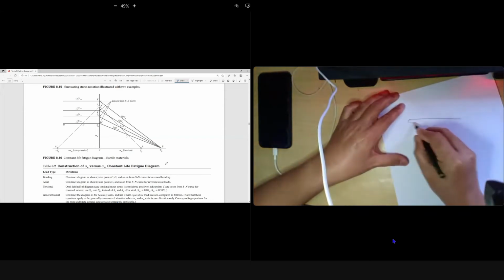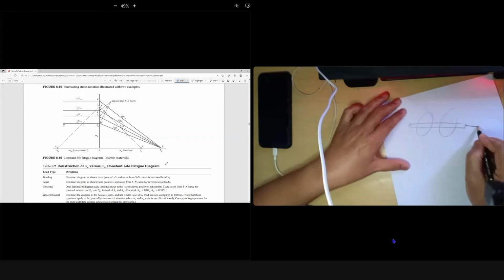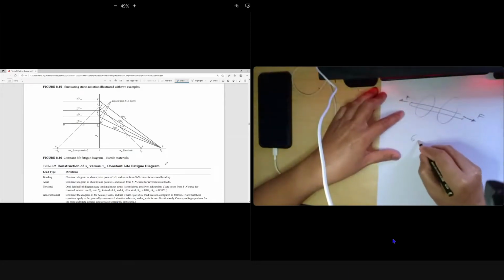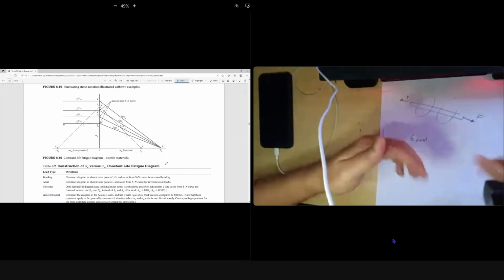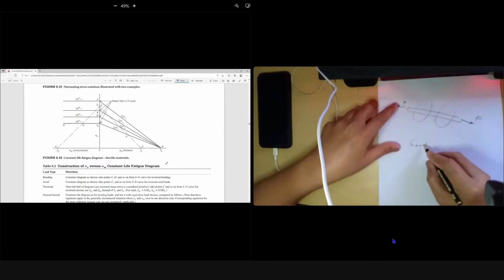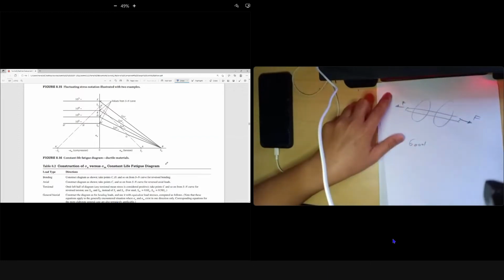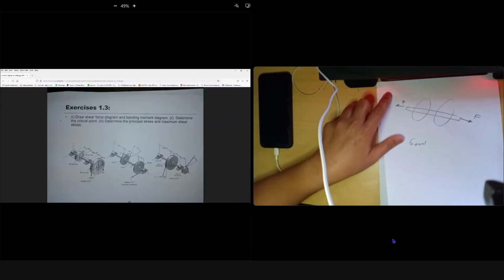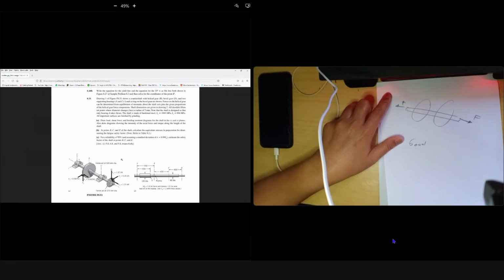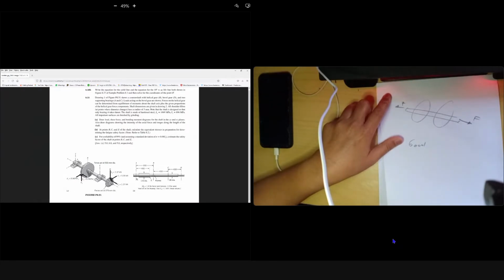Another case is where in the shaft you have, for example, two pulleys, and also the shaft. Remember, we already discussed, we have axial force, so we have sigma axial. If you have a shoulder or groove, of course they have axial, because axial is along the shaft. But it depends. If the question is like your previous assignment on fatigue, there is a part where they want you, for this diagram, to draw the shear diagram and moment diagram at both planes, and then you have to draw the axial. I think I already shared the diagram of axial force.